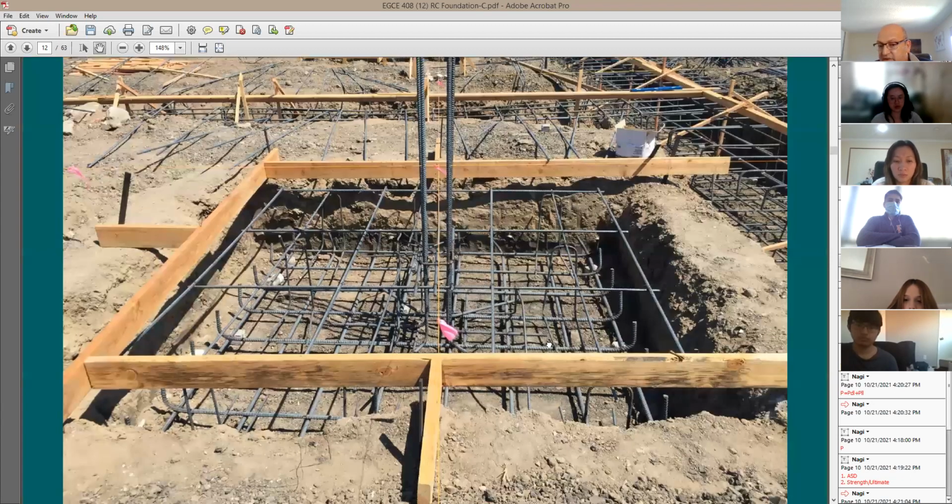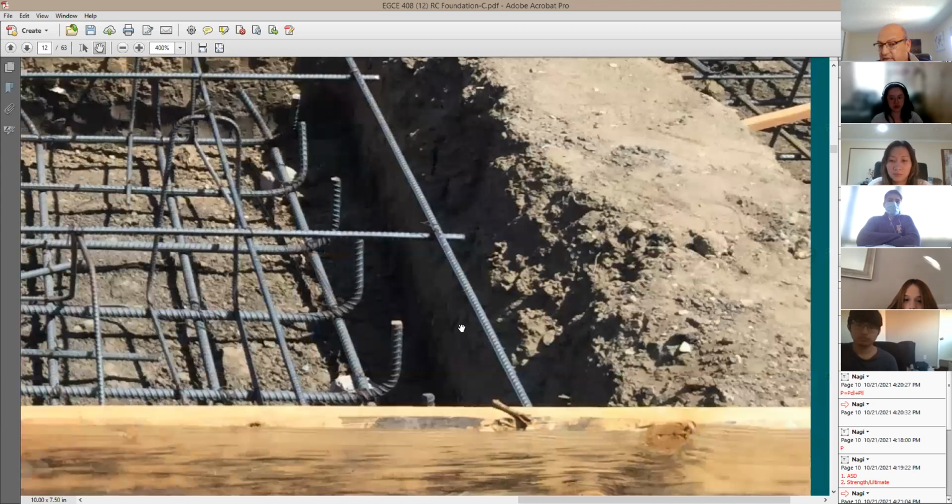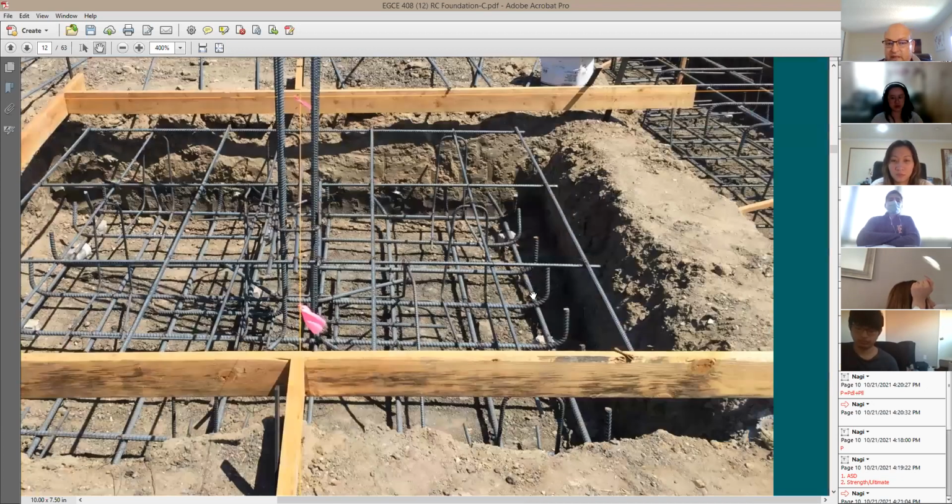You see this concrete cover, the distance from this rebar to here. But in reality, this is like 9 inches. They give me like here 9 inches. So I'm good. I have enough cover. So when it comes to the soil contact with the reinforcing, I don't have this problem. And as you see here, you have bottom reinforcing in both directions, right? And then you have top reinforcing. The number 5, and here are going to be the heavy rebars, the number 7.